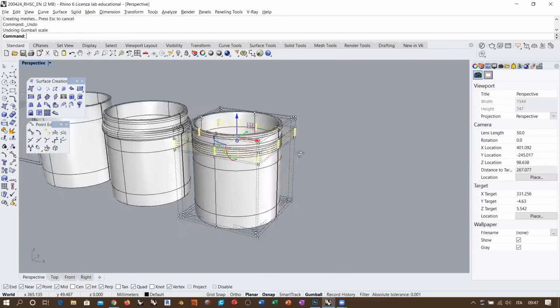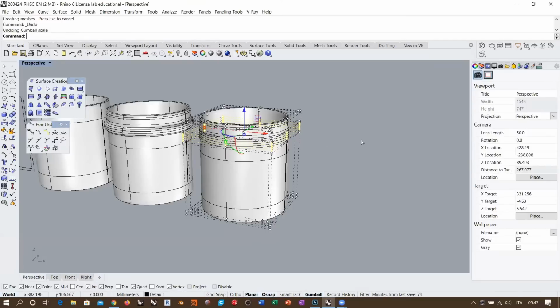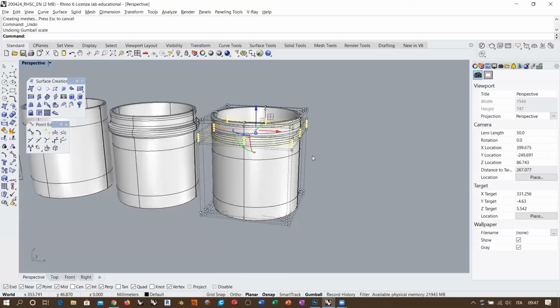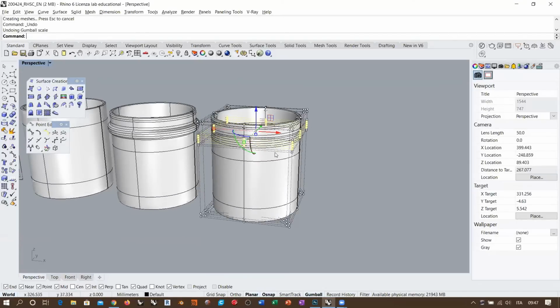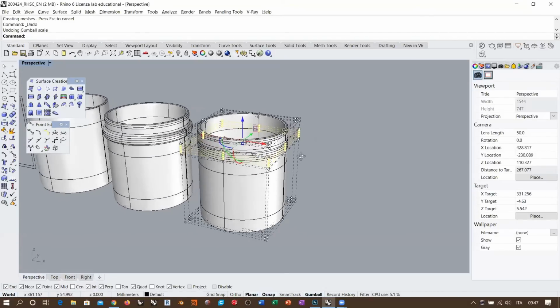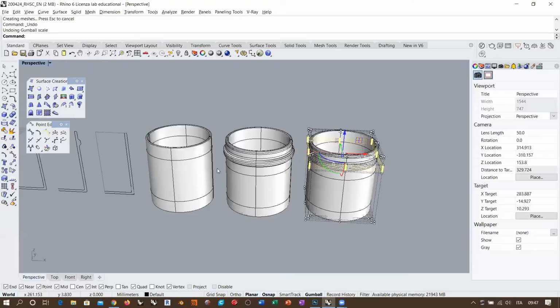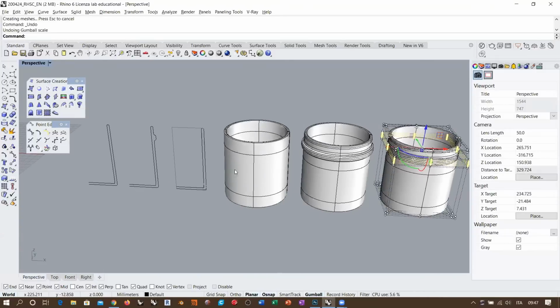But what I cannot do with this kind of situation where the profile has already the right topology is create local deformation. Why? Because this is the rule of a circle. So the deformation that I produce on one side will eventually affect the other side of the square, and eventually create creases. Okay, so I cannot use this method for creating local deformation inside the revolved surface.